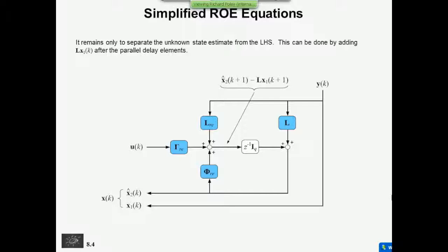So the reduced order estimator, once you calculate the equations, will have fewer equations in it. Yeah, it's faster, less computational load. The minimum saving you get is 5 partial products. I've worked it out. But the maximum saving can be large if the order of the system is large and you're measuring a lot of states. It's usually worth doing, even if it's only for 5 partial products.